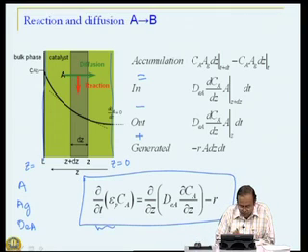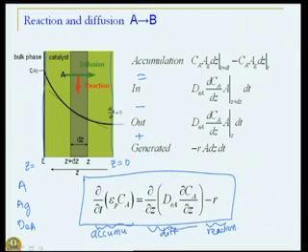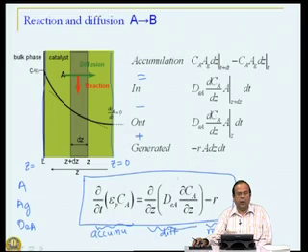This quantity representing accumulation, this quantity representing diffusion, and this quantity representing reaction. So, we have a mathematical model of diffusion, or a diffusion reaction equation, unsteady state equation. What kind of equation is it? It is a partial differential equation, time and axial position z, involves void volume, concentrations, diffusion coefficient, and rate of reaction.